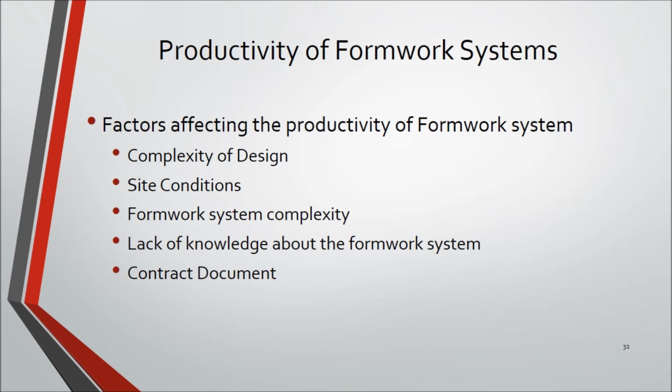Formwork complexity makes it difficult to erect and strip the formwork swiftly, thereby increasing the cycle time. Lack of proper training for new types of formworks leads to faulty erection of formwork, which then warrants rework. And contract document, well, we will come to that later.